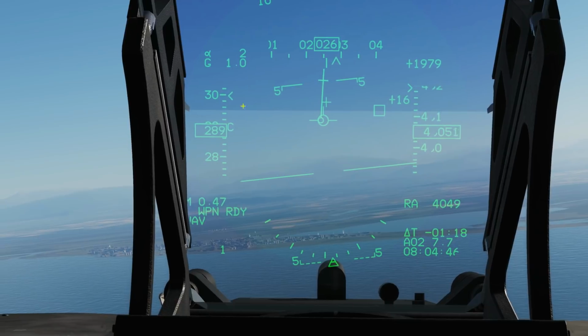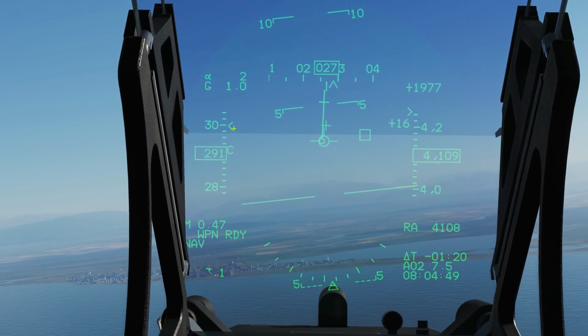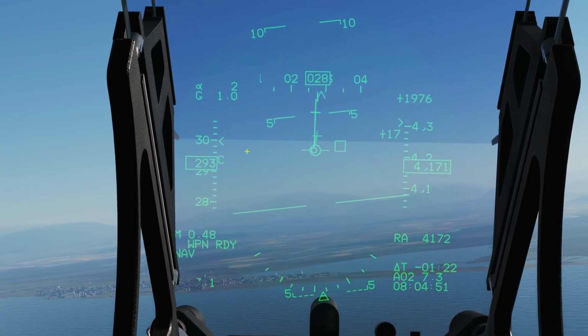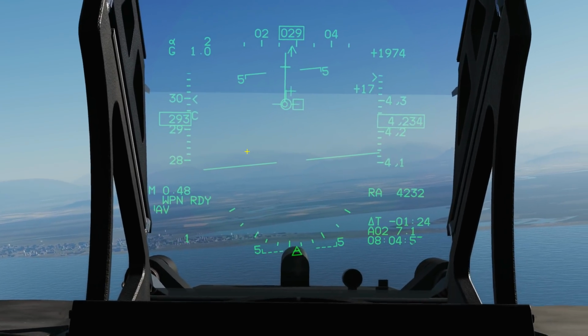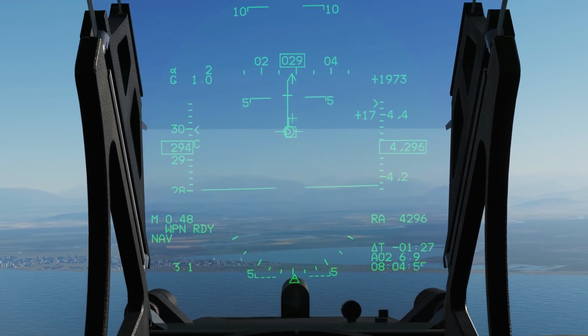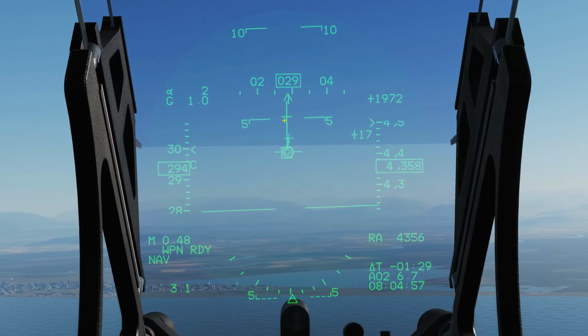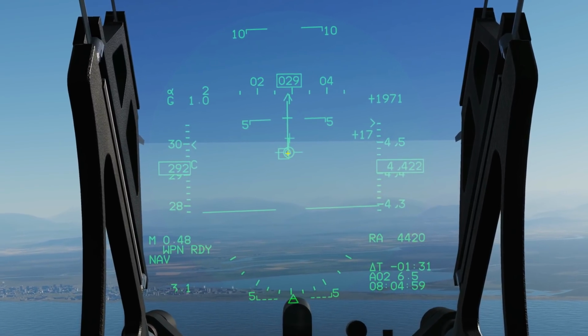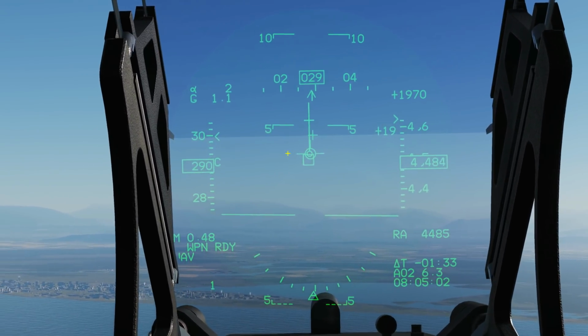Speeds I forgot to talk about. Here is the guided speed. By this waypoint, you want to be doing that speed there, 300. So that's something else that you should need to think about if you're doing a mission properly. You see, I've got everything aligned now. We've got this chap here vertical. We've got the distance coming down there. We've got our course guide in the center, and we're nearly on speed.